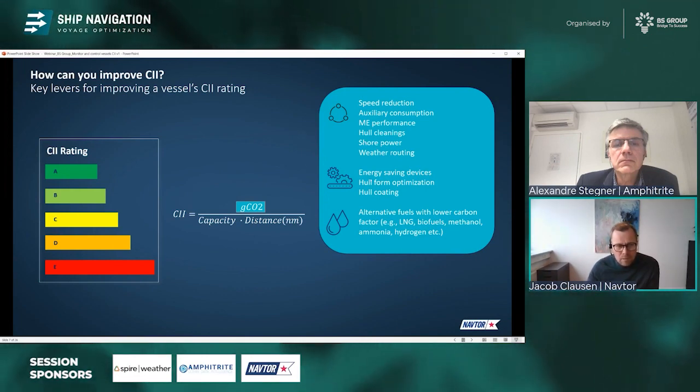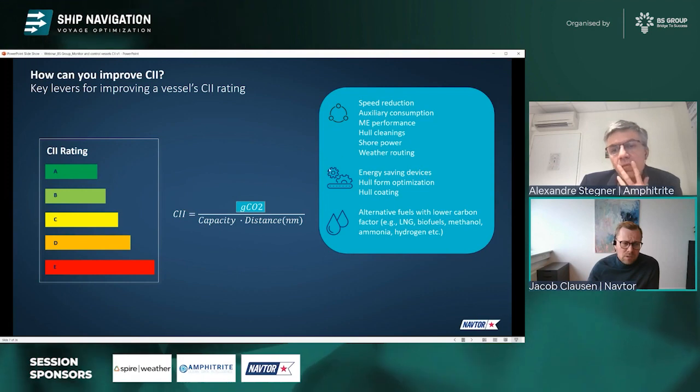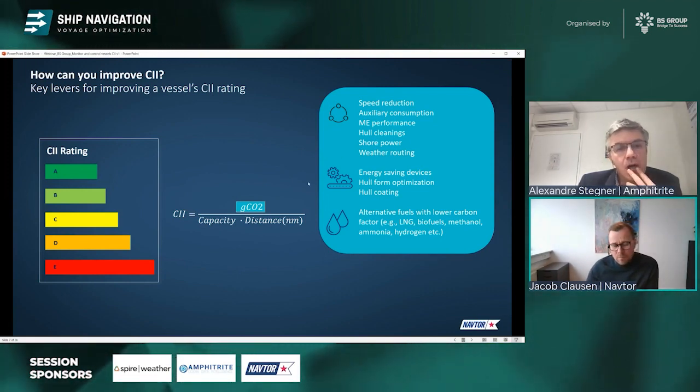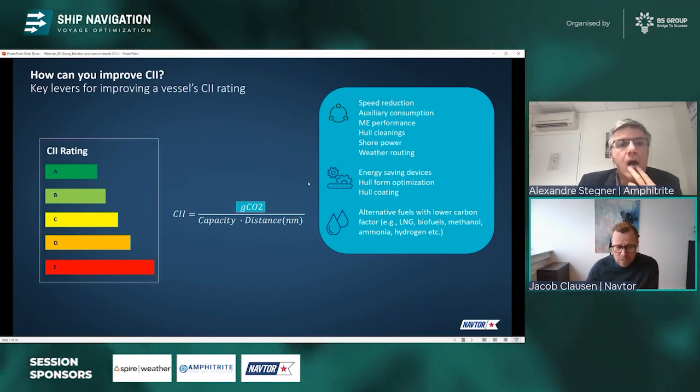The other part on the more technical aspects is energy saving devices. So this is typically the CAPEX projects here: energy saving devices, hull form optimization, new propellers, special hull coatings. And then of course there are the more operational factors as well, like alternative fuels, which we see increasingly being used.